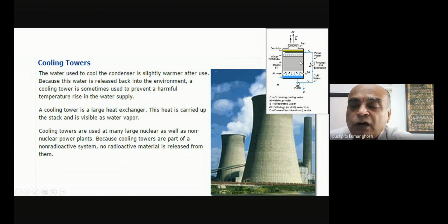The water which is falling and which did not become vapor is becoming colder, because it released its heat to the other water which got vaporized, in the form of latent heat. Because latent heat is very substantial, it leads to a significant reduction in the temperature of this falling water. And that is what is known as the cooling tower.